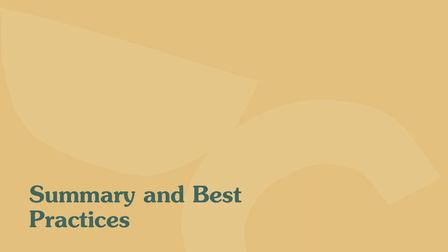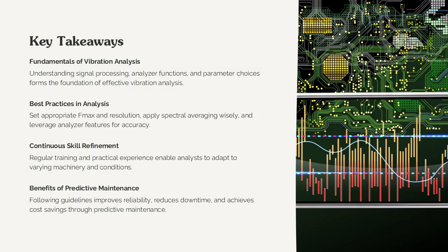Summary: best practices and key takeaways. Effective vibration analysis relies on a solid understanding of signal processing fundamentals, analyzer functionality, and parameter selection. Key best practices include setting appropriate Fmax and resolution, applying spectral averaging judiciously, and leveraging analyzer features for accurate diagnostics.